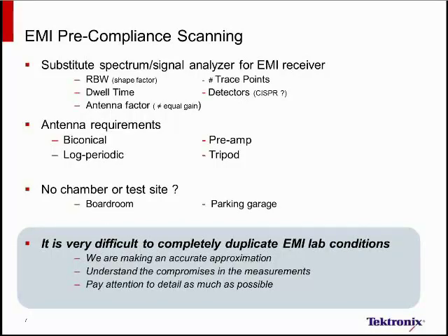Ultimately, it's very difficult to duplicate exactly what the EMI test setup is in the test house. We can make a very accurate approximation, but it's not the same. We need to understand the compromises in using a signal analyzer versus an EMI receiver, and we have to pay attention to as much detail as possible.